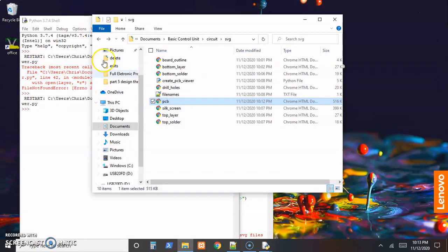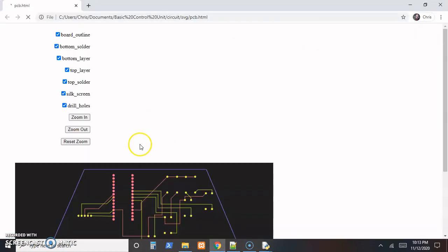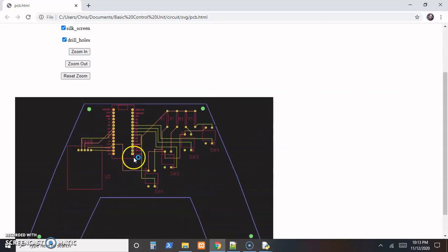So along with that, these same files will be used to generate a 3D model in Blender, which I'll use to do all the CAD work of design and get the product ready to order from a factory. And I find it a whole lot easier to inspect a 3D virtual model than the 2D images myself. We can see everything and go through it carefully here. The big point is, if you're going to inspect the image, you can do that in EasyEDA, but it can be a bad idea to inspect the circuit someplace where you have edit abilities. So do the inspection where you can't accidentally edit a mistake in.